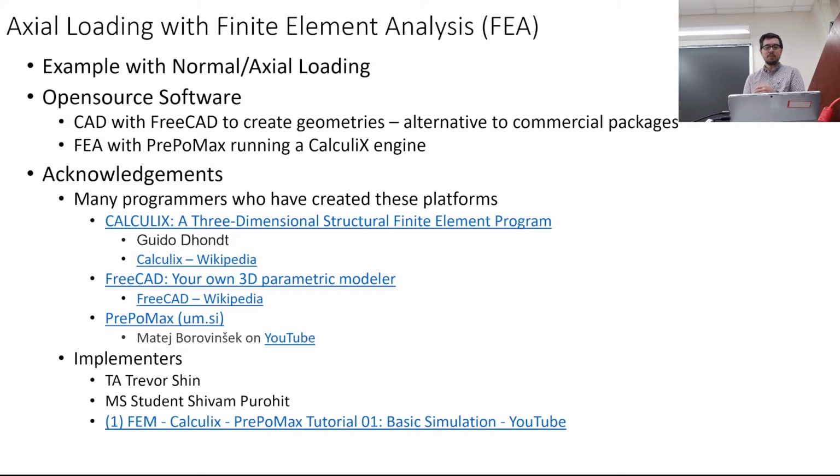So what we're going to do today is use an engine called Calculix that is embedded in a couple of graphical user interfaces. FreeCAD has Calculix in it as well, but we're just going to use FreeCAD for creating geometry, and we're going to use PrePoMax as a user interface to be able to look at the stress and strain in a bar that's being loaded with a force.